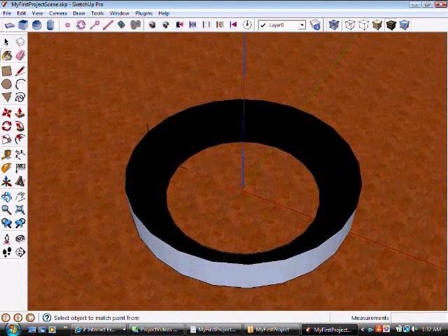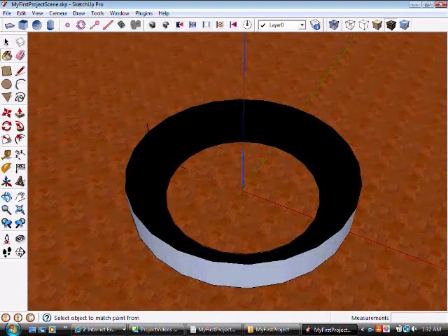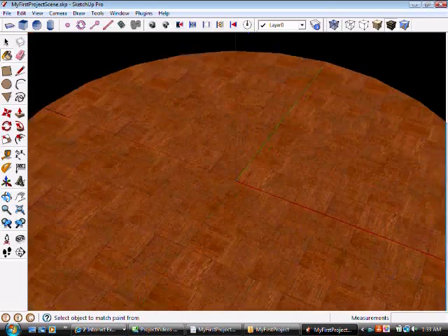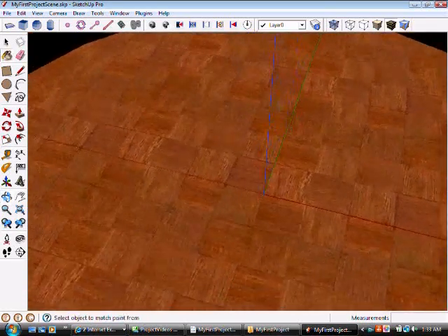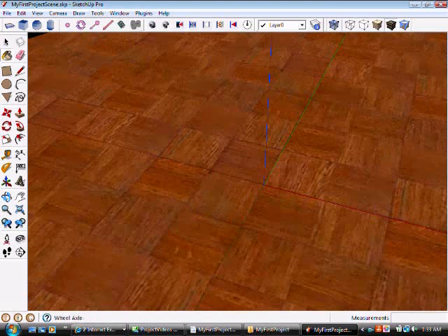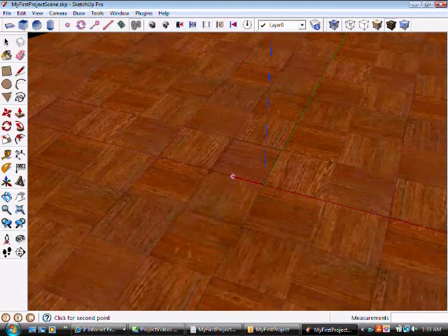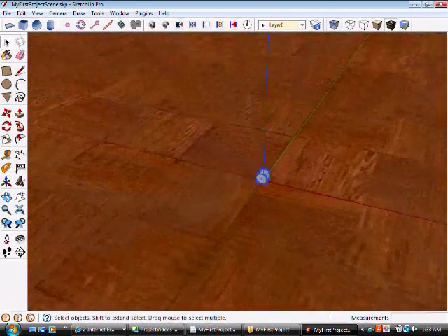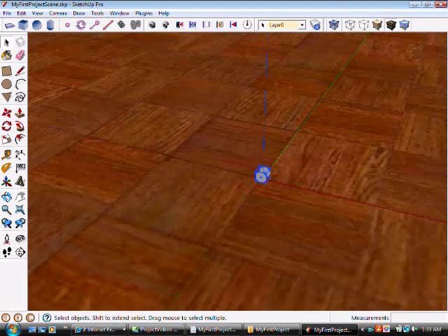Now let's build our vehicle, which will be a differential drive with various sensors mounted on top of it. When you create a vehicle, what you want to do is use the wheel axle and point it in the negative X direction. There's a technical limitation in which that is necessary to build your vehicle. Later, when you group it, you could orient it any way you want to.